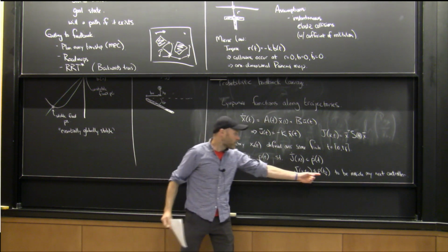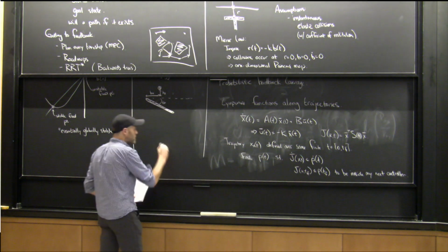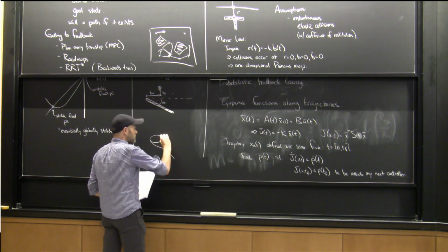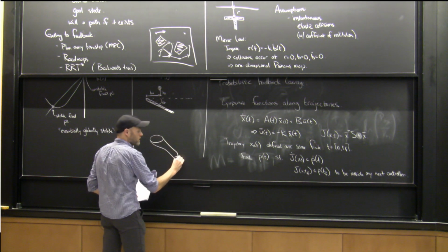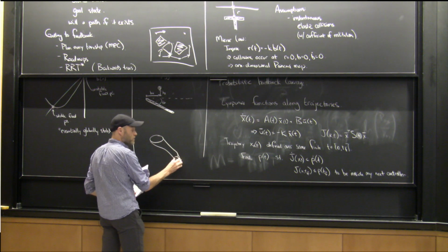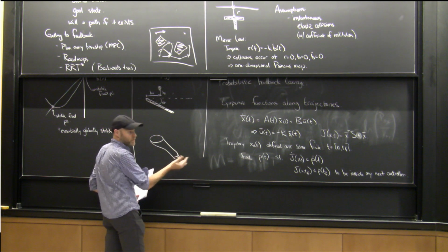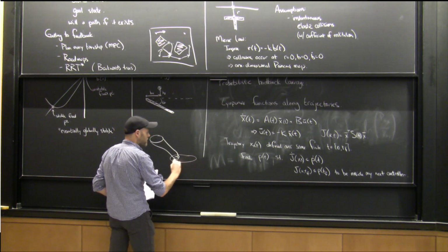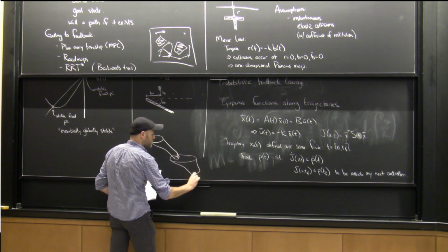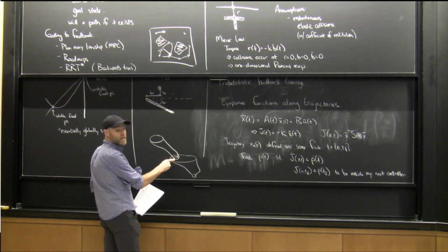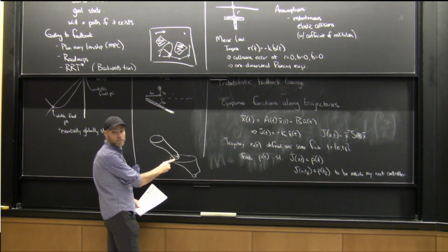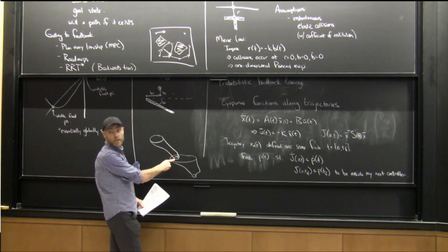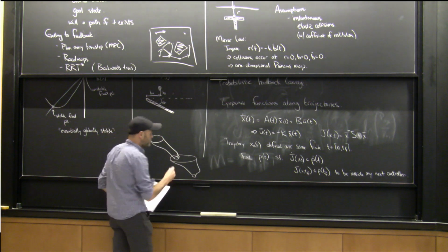Okay, so I do care very much that the outlet of this funnel, when it's done, is some sub-level set of J, which defines some ellipse if my J is quadratic in this case. It needs to be inside another ellipse, right? That turns out to be a simple constraint to write. Ellipsoidal containment is something we can write with convex optimization.